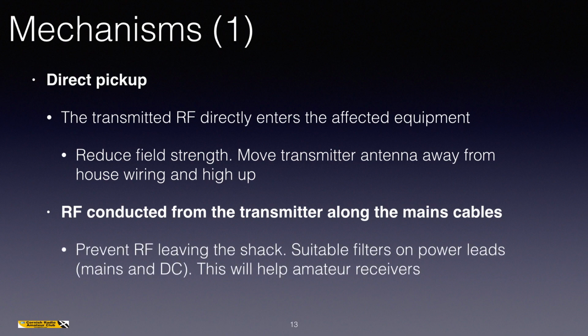Now you can prevent the RF leaving the shack if that's one of the problems. The shack is essentially where you've got your radio equipment, by putting suitable filters on power leads, both mains and DC. This will also help your own receivers.